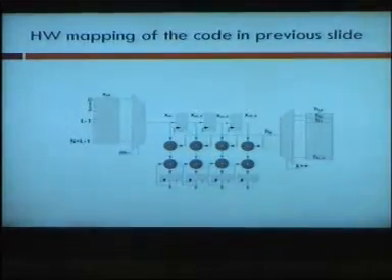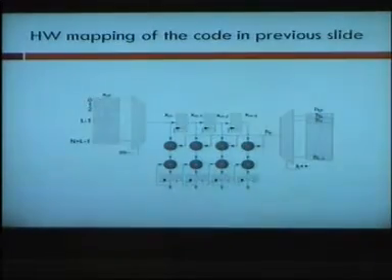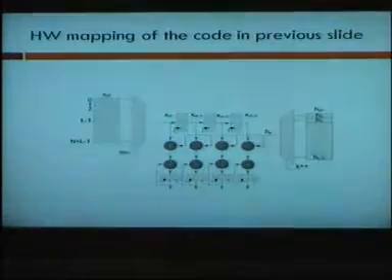This is a requisite. So you say, I have drawn this, then it is just a language like C, which most of you must be knowing. It's Verilog. Then you just sit down and write your code. And it's much easier to write Verilog than to write C. So that's another comfort, that there are no pointers, no pointers to functions. There are so many things which are not there in Verilog. So Verilog is a dumb, simple language. The reason it is dumb and simple is that it has to be translated by a tool into hardware, so they have to keep it very dumb. It's very simple to learn, especially the part of the language which translates into hardware.